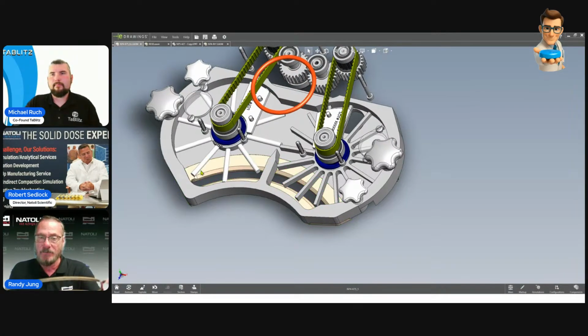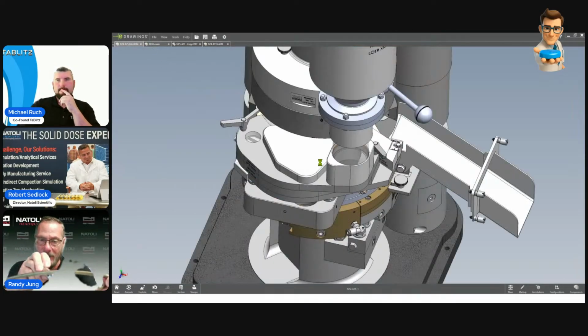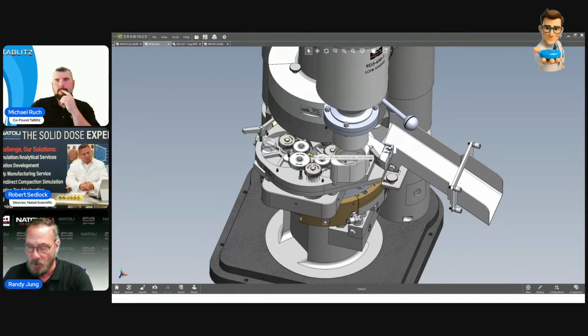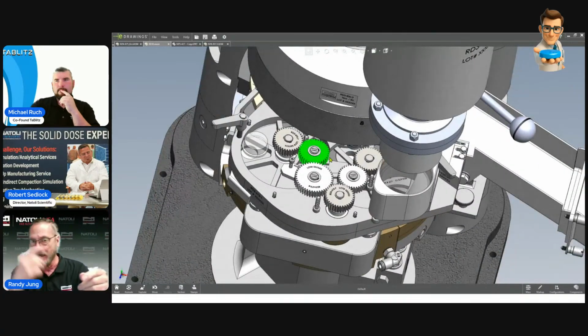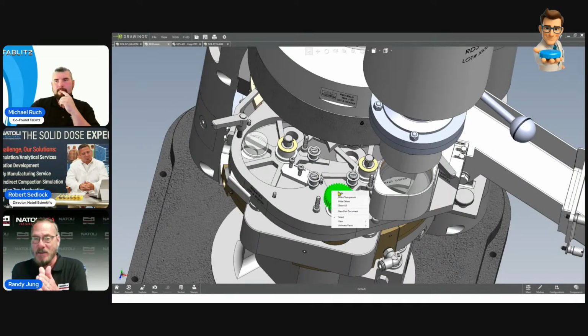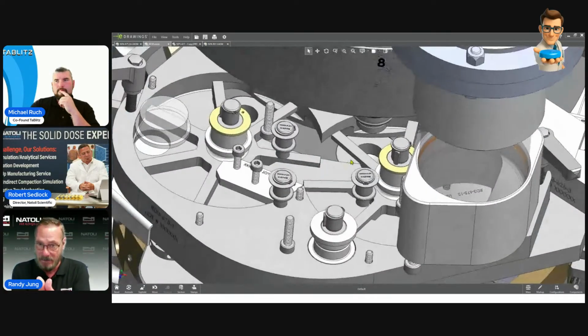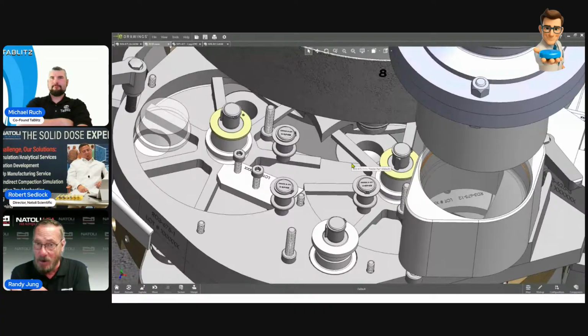Because you can imagine if I have this very large opening and then I have this very small tip, I have all this powder that's sitting on the die table. My die table is spinning at 1,600 millimeters per second. The powder is going to pick up the velocity of that die table, and it's going to be moved to one side of the feeder at 1,600 millimeters per second, and it's going to be pushed against it. Densified. If it can't get out, it's going to start to densify.